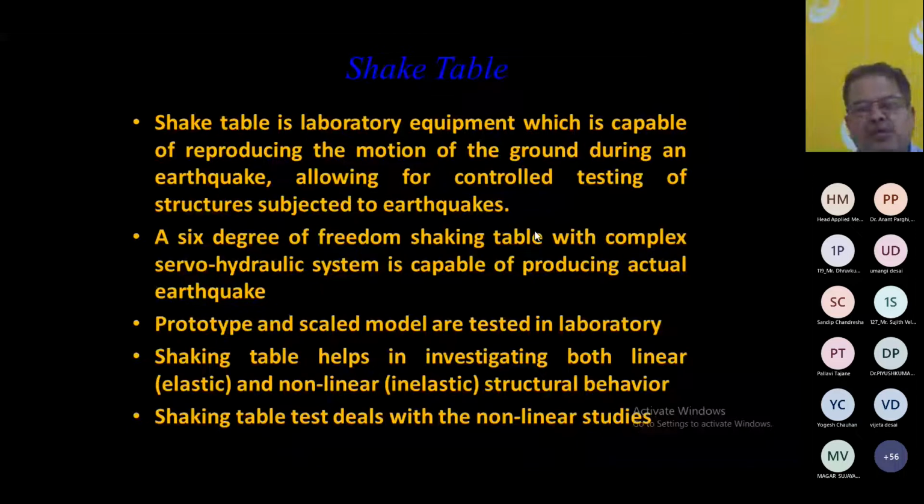But if I'm talking about the lab we have at LD College, we are not exactly applying the ground motion, but we are applying the sinusoidal excitation, right? So it is a harmonic excitation. That depends on the type of facility you have, right? So it allows for the controlled testing of structures subjected to earthquake. So that is needed.